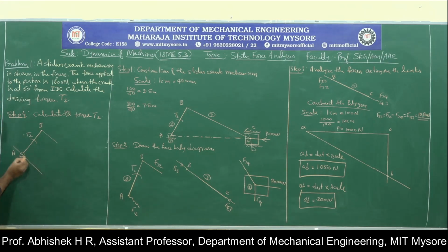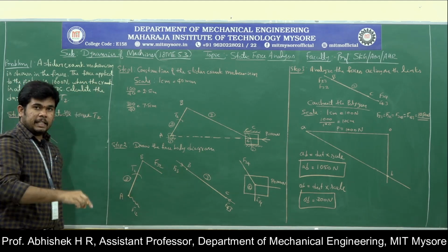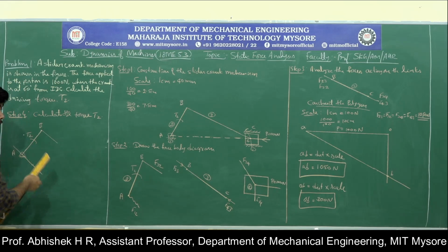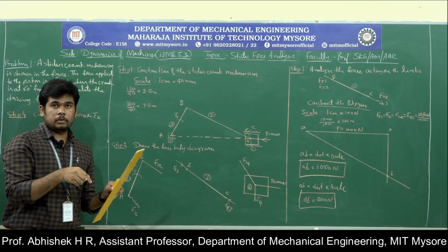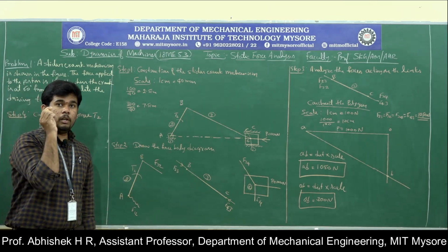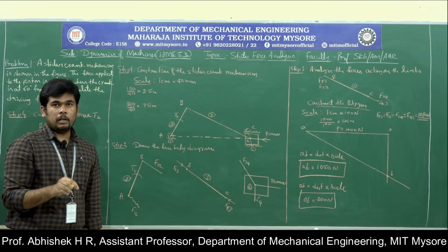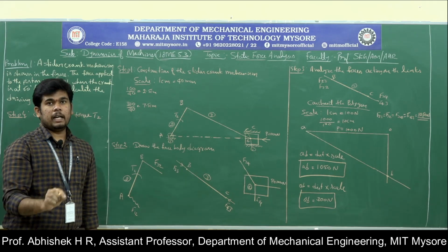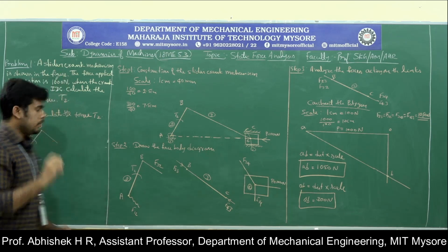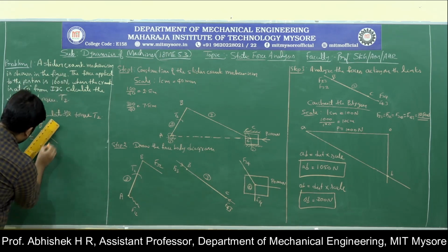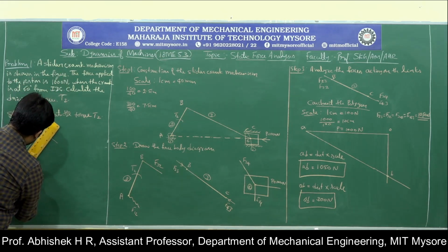Now here just make a point, and at this point use your protractor, measure the 90 degree angle, because don't draw a rough straight line because it will not give the correct height value. So first measure the 90 degree distance, then draw a straight line.